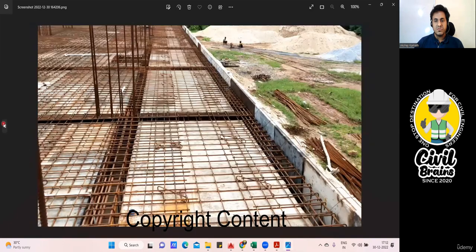Yeah, this image itself. You can see this L we have taken. So again, we would be calculating our cutting length from here to here. That is, from beam inner to beam inner. And after that, whatever we'll take, it is a development length. After that, this bar won't go completely. From here, the gap we are going to leave is a 40 cm gap. So that means my bar will go only up to here. So this distance will be how much? Whatever is the width of your beam minus one cover, this length I'll get.